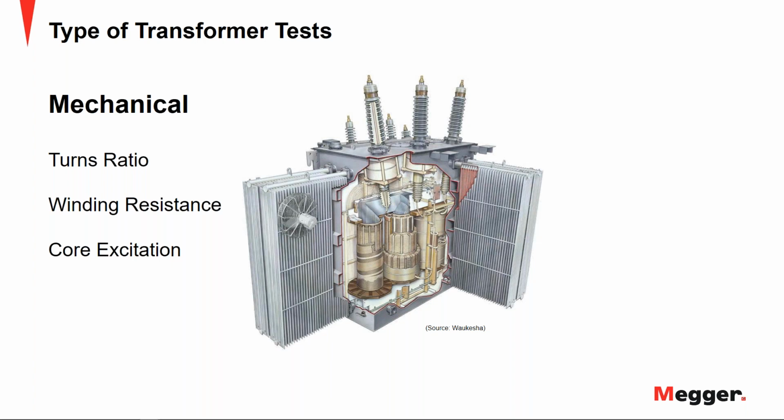So if you leave the setting to the auto voltage, then the test set looks for the optimum voltage that should be applied for a given transformer so that you get the best possible results. So I highly recommend starting the testing in the auto mode, because that would give you the most value out of your testing.